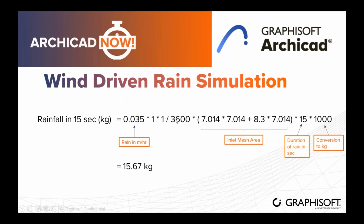So I'm dividing it by 3,600, and you can see, let me just highlight, this is the volume of rain per second in meter cube. So I need to multiply the surface area of my mesh through which the water enters. These two are the inlet mesh area of my side and then the top. I'm multiplying it by that, and then by 15 seconds, because it's going to be a 15 second simulation. And this is currently in meter cube, right?